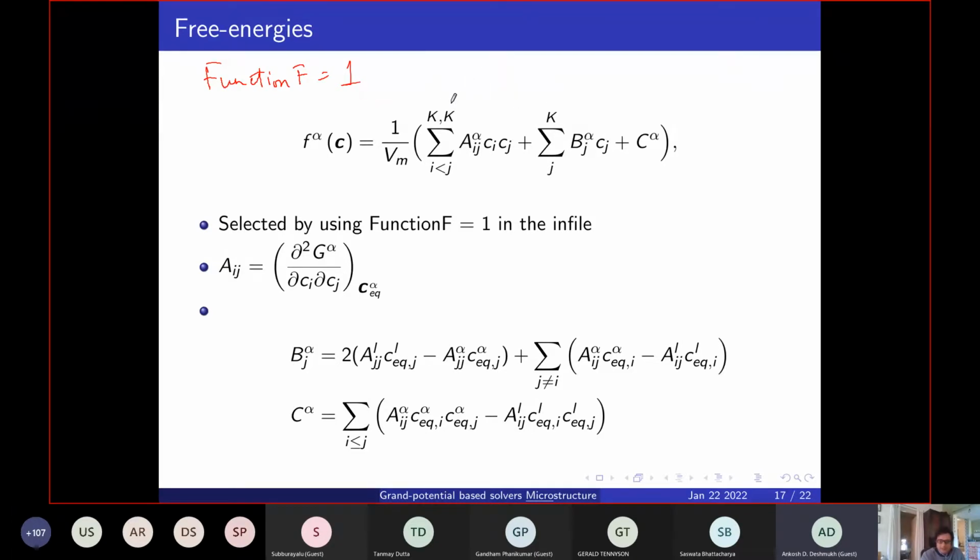That's all the approximation that you need for any given system, particularly for phase transformations, because if you write a generic parabolic free energy of a multi-component system in this manner, the curvatures of the free energy can be directly extrapolated from the thermodynamic databases, and the constants that exist in the parabolic coefficients can be estimated from the equilibrium compositions, which can again be derived from the databases. So in some sense, most of what is already part of the thermodynamic databases can be included into a simplistic free energy of this form.